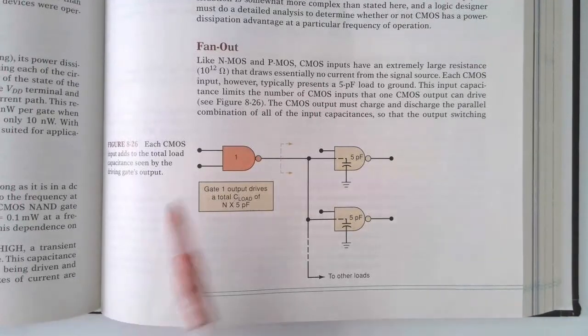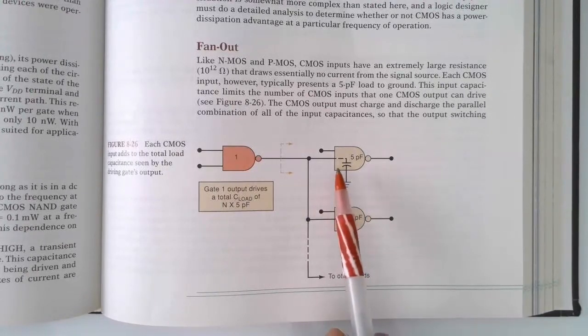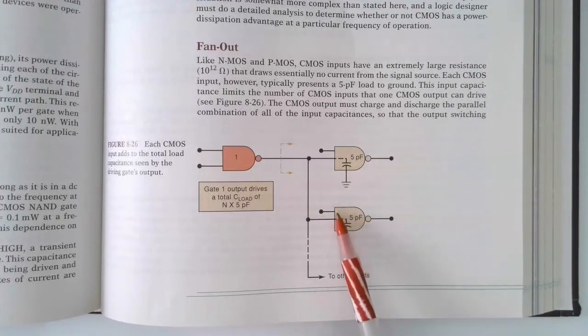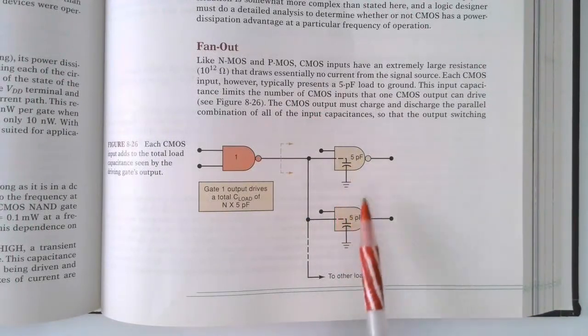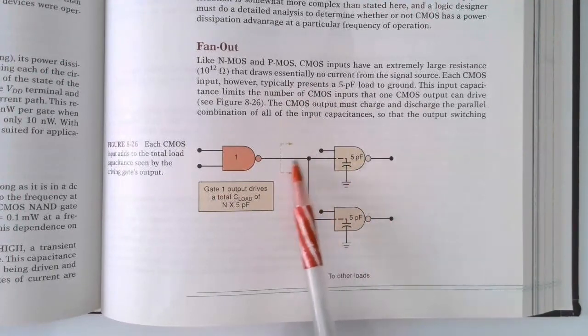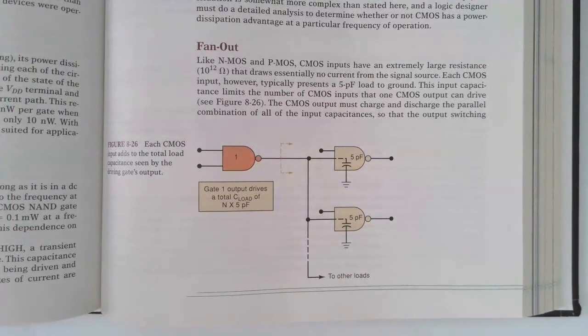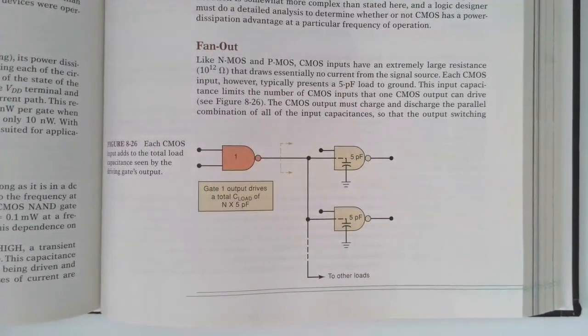And so the effect that this has on CMOS circuits is it can limit the frequency response of how fast these devices turn on and off. Interestingly, you can go all the way up to 1 megahertz and have 50 devices connected. But if you're trying to operate something at 30 or 40 or 100 megahertz, then that would become a consideration. The time it would take for that gate to turn on or off would actually slow down. So it's not a current problem here with the fan out, but it's a time problem, or a frequency response problem.